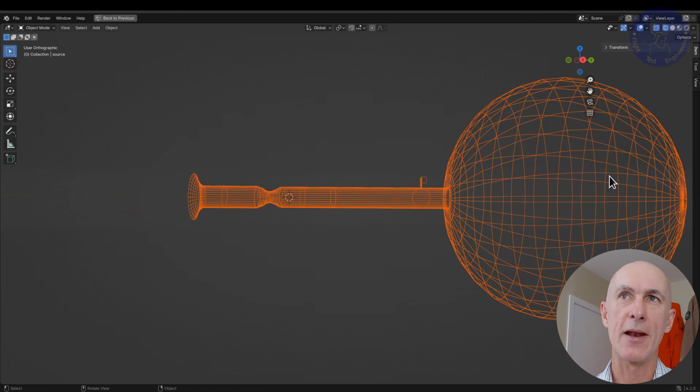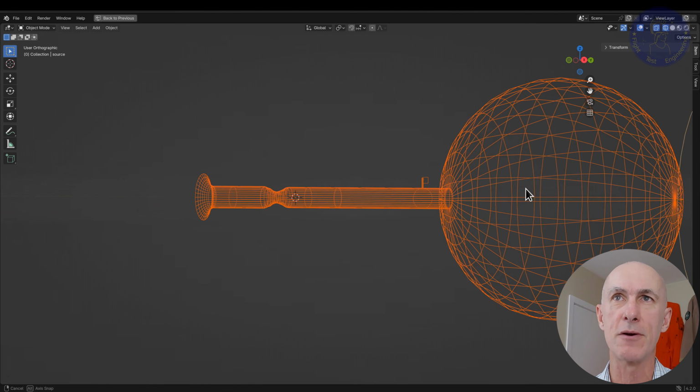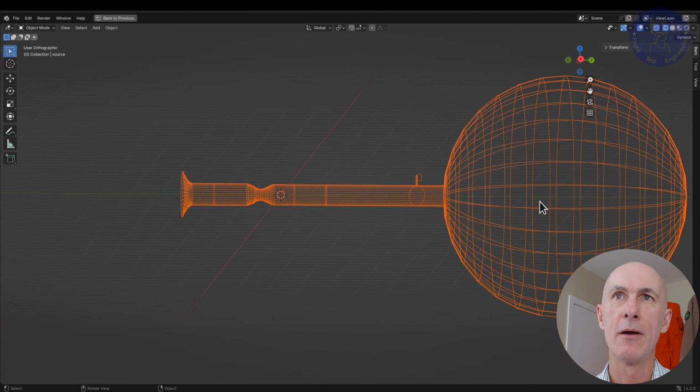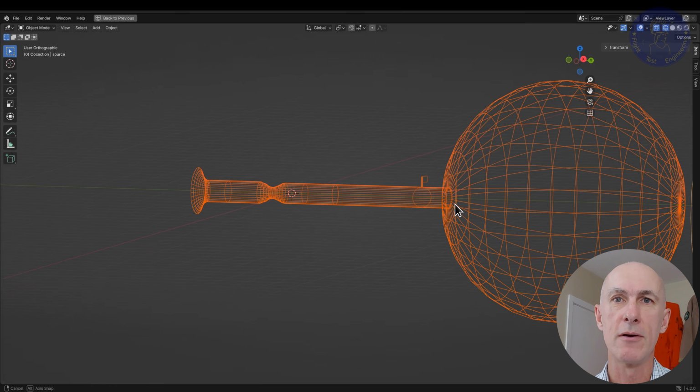Let's start with a simple setup here. Suppose that on one end we have a tube open to the ambient, and on the other end we have a big vacuum reservoir that can be kept at very low pressure by very powerful pumps. Air can enter the tube and flow into the low pressure vacuum, and in between we have a transparent convergent divergent nozzle where we can peek into what's going on with the flow. We can control the amount of air passing in the nozzle by opening and closing a valve at the end of the tube right before the vacuum chamber, which is right there.